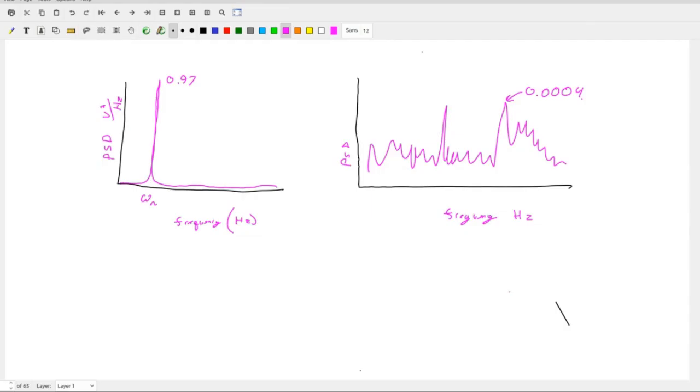That makes sense. Okay, and that's a good power spectrum density for completely random noise, for white noise. But it's a little hard to deal with in terms of mathematical calculations, and we have a lot of points. So what we want to do is take an average right down the middle. I don't like that. Maybe let's just do a fat line. Oh, that looks much better. Right down the middle, and call that S0. And that's going to be the average of our signal.